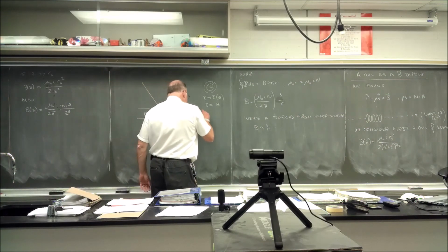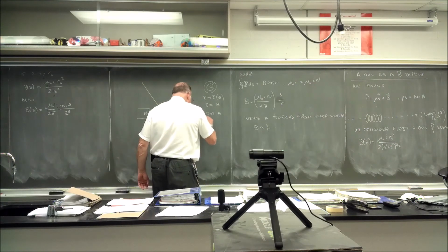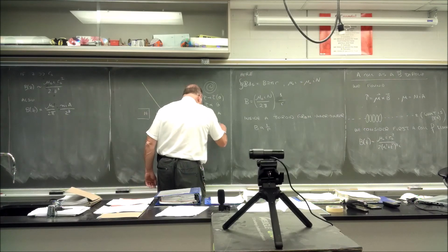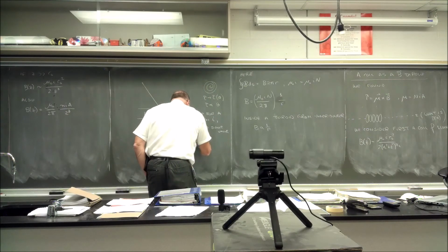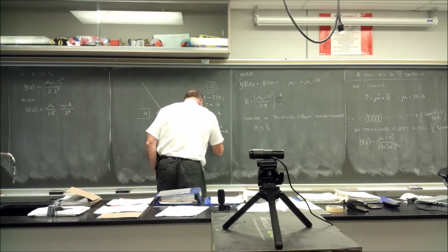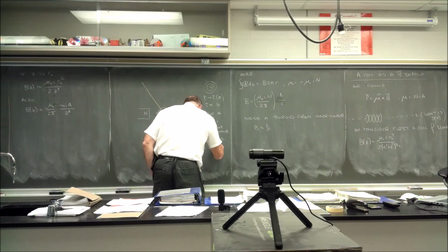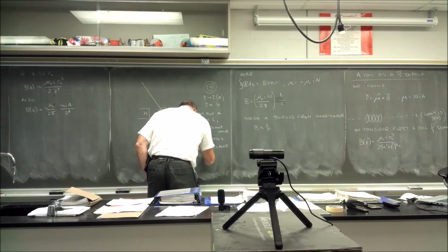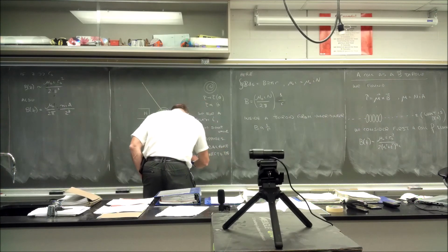So for a given current, you have torque due to I, some value. And then the torque of the spring opposes. It will balance. And the wand points to the value on the scale.